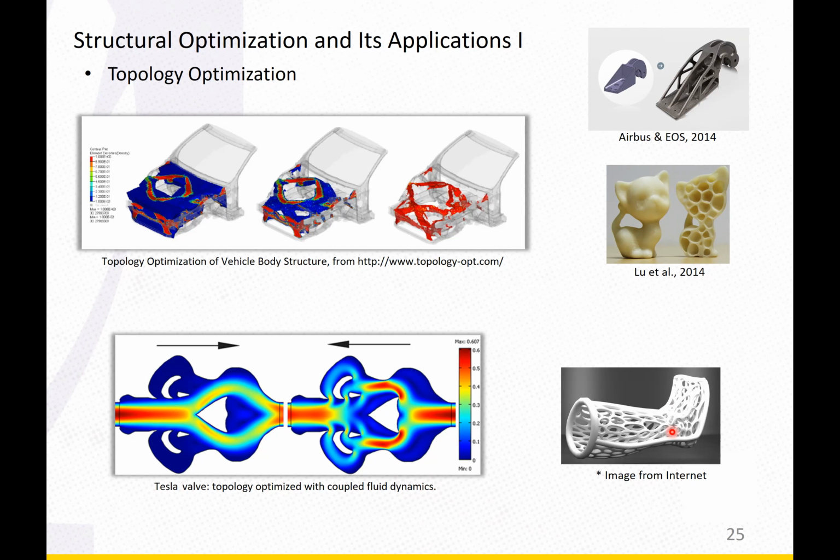So that's why if we could put some hollowed patterns here, the heat can be emitted from those hollowed patterns, and that will give the patients who wear it a better experience. Then how do we distribute these hollow patterns, and what are the shapes and sizes of these patterns? All of these questions need to be answered by a certain topology optimization approach.